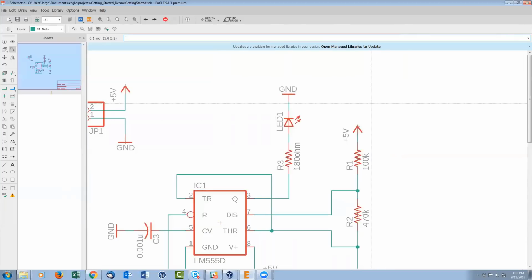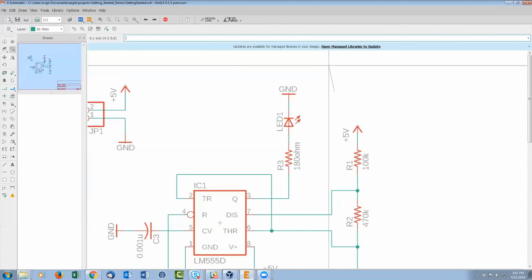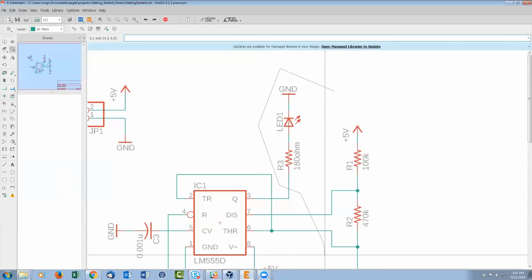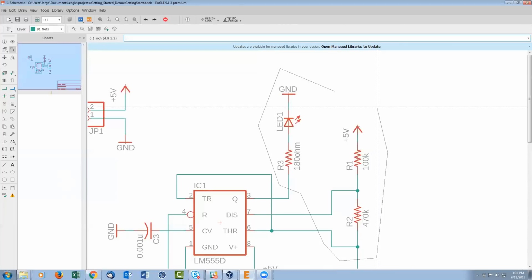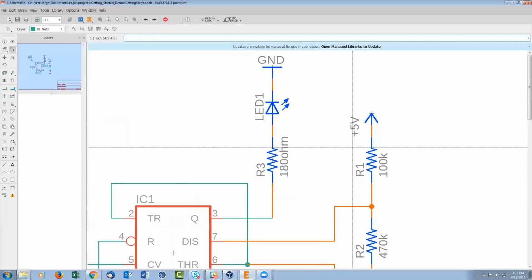The last mechanism, which I think is the most unique because I've never seen it in other tools, is what's known as polygon selection. So what you do is you don't drag, you just left click in space somewhere. And you'll see that this line starts to form. Whatever you enclose with these lines, say I wanted just this part here, when you reach the end, you just double click to close it. Whatever shape you draw, that will be selected. If you've seen the new Zillow commercials for Realtor.com or whatever, where you can draw out a search area, it's basically the same thing.